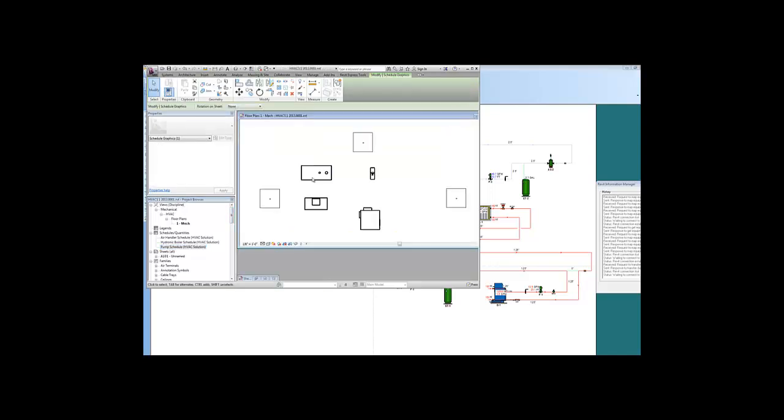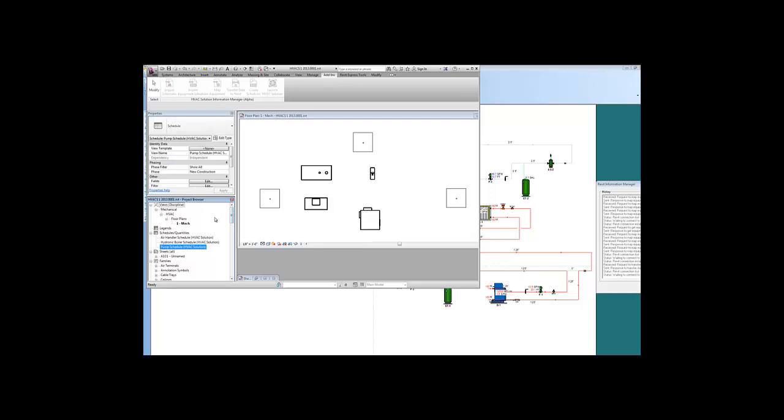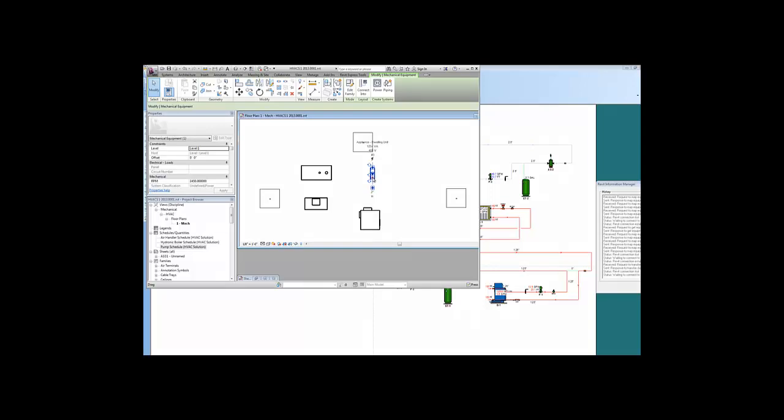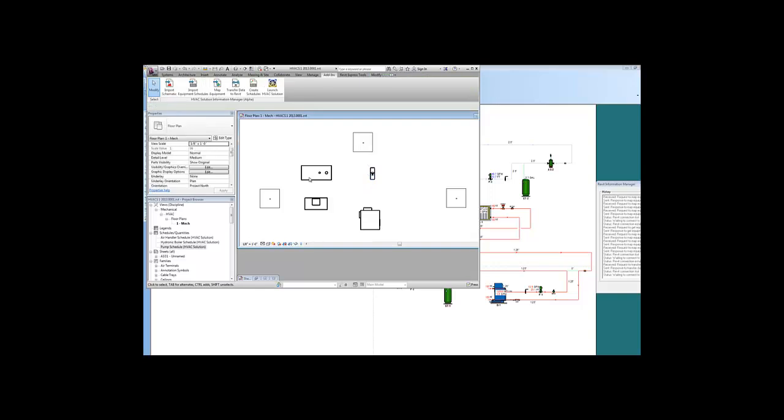Next, let's close out of here and click on the pump right there. Come under pump, and you'll see all the data has been put in. There's the HVAC data provider, pump, Taco, head, flow, horsepower, all the data is right there as well. Click on the boiler as well so you can see that.